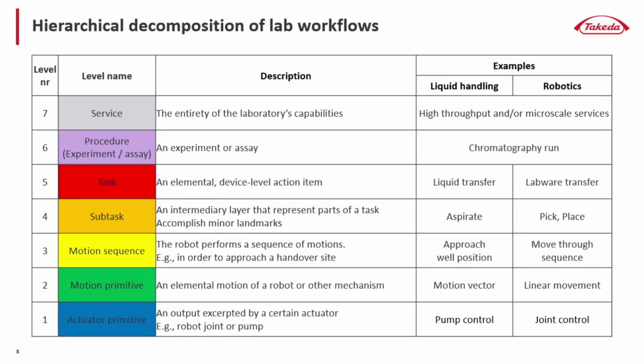So an assay consists of tasks, and tasks consist of subtasks. Here we outline examples for liquid handling, and what we will especially focus on, labware transfer. There we see that subtasks are implemented by means of motion sequences, so trajectories that the robot arm completes. Those can further be broken down into motion primitives and ultimately actuator primitives.